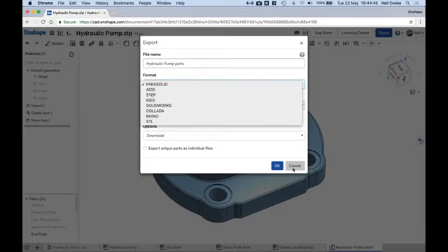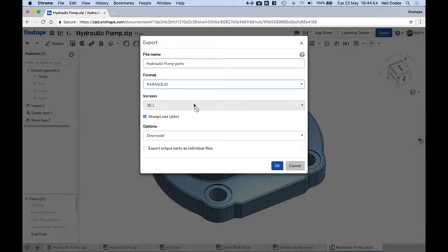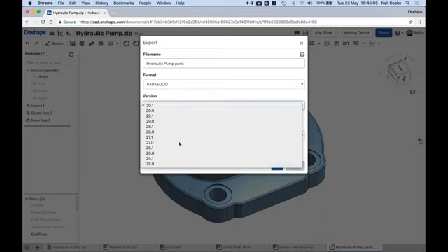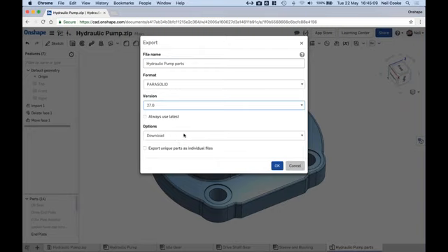So when you share it with somebody with export rights, they can do the exporting themselves. They might try Parasolid version 30 and then suddenly realize, well, actually, because Onshape's updated every 3 weeks, we are always on the latest version of Parasolid, whereas they might be on version 27 or something, but they can mess around with that.